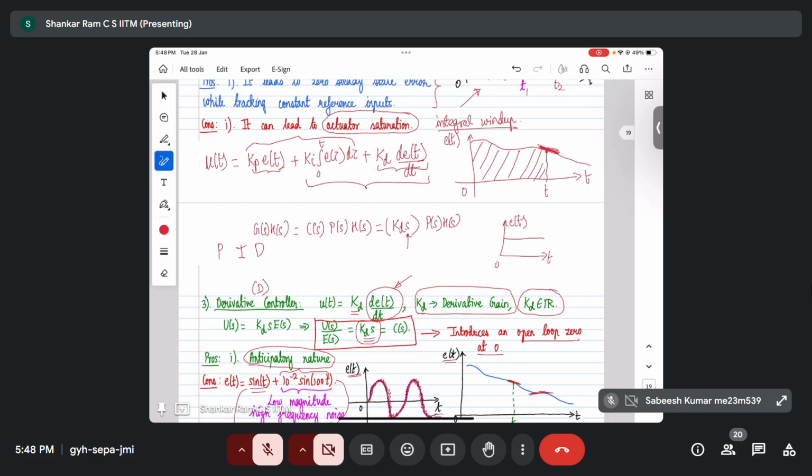Prem here. So this KD value, or any constant that we are multiplying as a controller, those three parameters, will typically get affected by the actuator or the end system alone, which we are trying to control. That will also play a role. So the plant dynamics will play a role. The actuator capacity may play a role. And there may be other constraints coming in due to stability and performance considerations. So we are going to look at all those things as we go on.